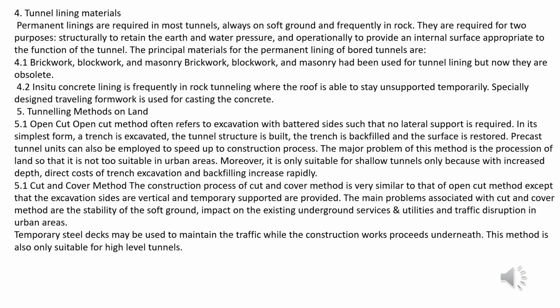In situ linings are the ones made on site. The in situ lining is frequently used in rock tunneling where the roof is able to stay unsupported temporarily. Specifically designed traveling formwork is usually used for casting the concrete.